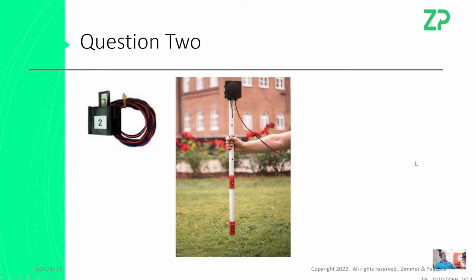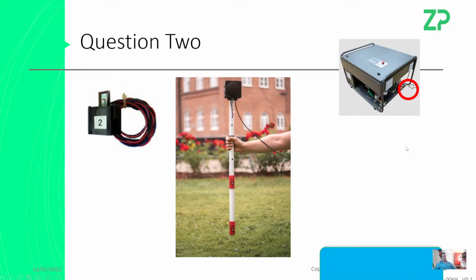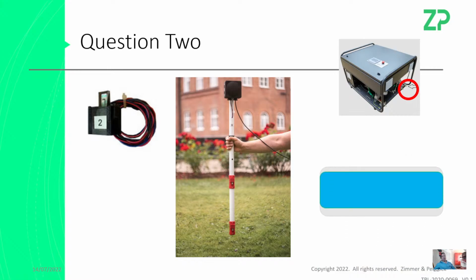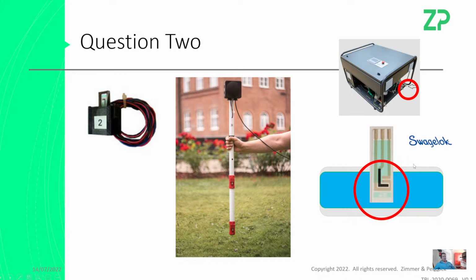Now, the way I would do it is this: there's an outlet on here, and I'd potentially make a tube. I put Swagelok in here because I have a suspicion there are some Swagelok pieces on here. That's just a brand that people use in process engineering quite a bit. And I'd literally just have the sensor going through the wall of the tube. That would have to be epoxied in. But you have to think about this piece quite a bit because if the sensor is really robust to the application, then it's permanently in place. But if you find the sensor degrades with time and you have to replace it, then you don't want that.